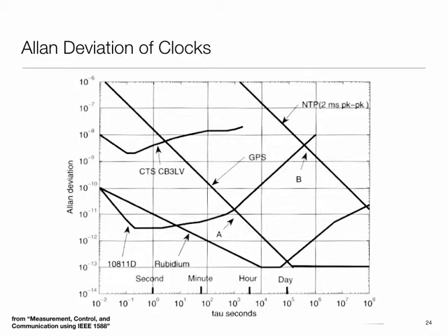Cameras operate at some frame rate. So right there, I have a 30 millisecond issue, because the frame rate is typically 30 milliseconds. So maybe I'll need a high frame rate camera where I could do those kinds of experiments. Alternatively, we can use some sort of interrupt pin coming to the CPU of my laptop, send an interrupt from some external source, and conduct that kind of experiment.